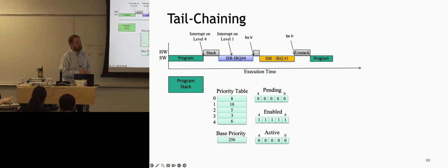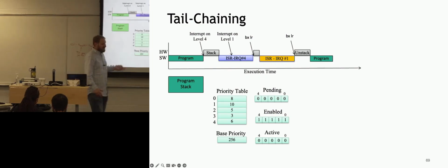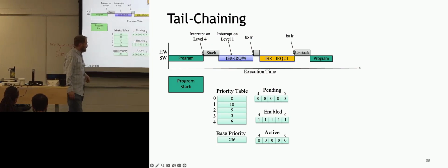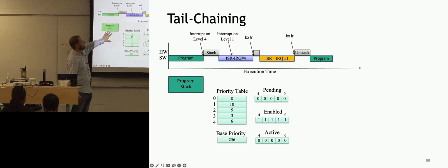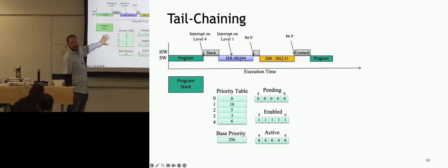Yes? That waiting period, what's all happening? Is it just setting PC? Yeah, setting PC, probably got to update the base priority sort of things. But you don't have to hold the state of the microcontroller, right? You don't have to update that. You can just leave it on the stack.